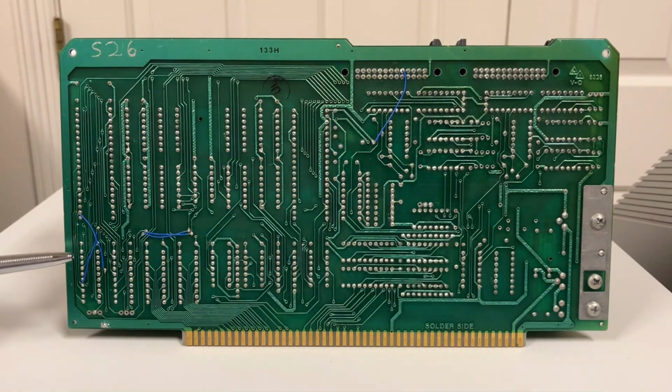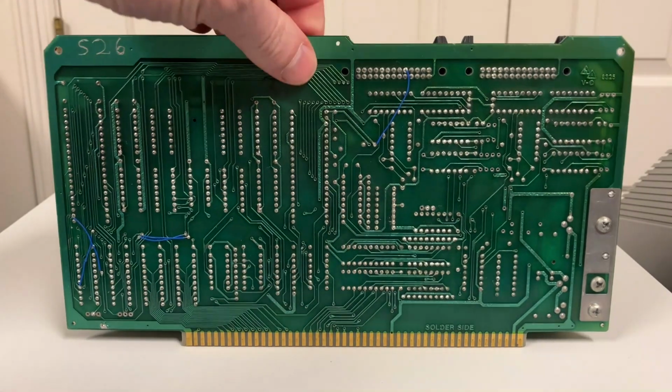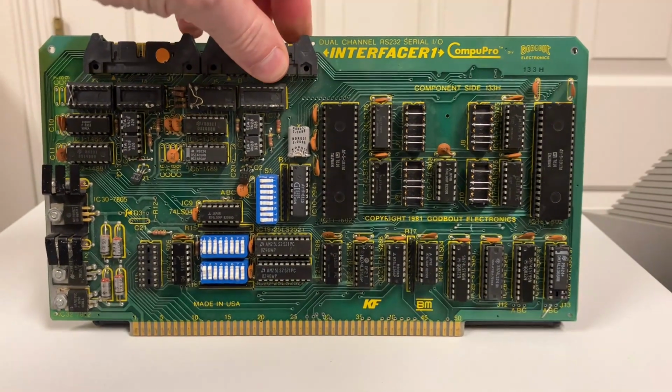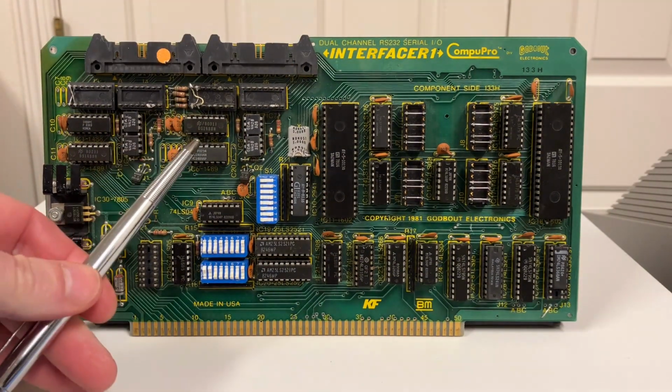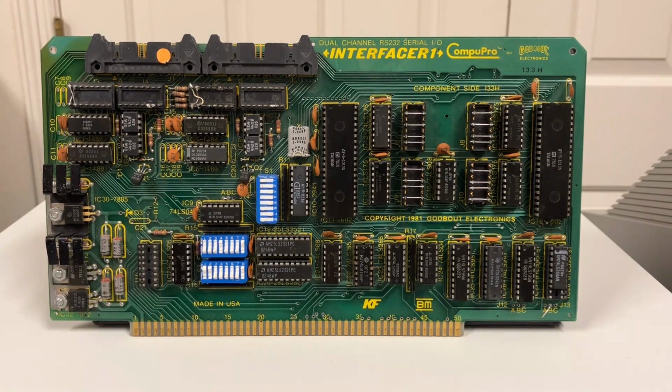You see a few blue wires. Ignore most of those, except for there's 2 over here that are the ones that routed transmit data to bit 7 and receive data to bit 0. I had to cut a trace over here to free up one of those pins. And rather than cut a second trace to free the other pin, I was actually able to just lift a signal on a chip right here that goes to the pin we needed to use. That signal is not used for anything else, and so I can just lift the pin out of the socket, and that saves having to cut that second trace.